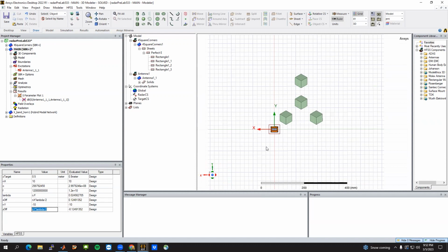I'm just making sure that the 4 corners cover the area of the targets. That's not really necessary, because in this case we'll be using an algorithm called back projection. Back projection doesn't really care about that, but it is important because you want to make sure the beam is illuminating all the targets, no matter where the antenna is. That's why we want a very broad beam width, so that all targets fall within the beam when you're taking an image, when you're collecting the data.